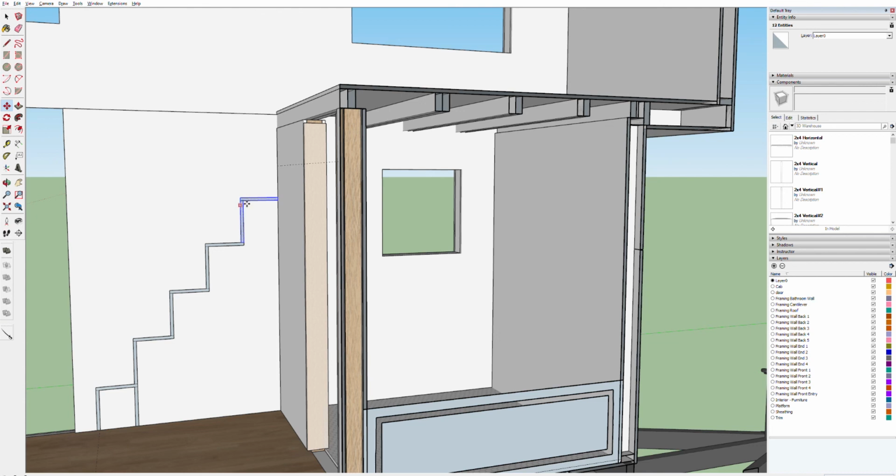Ooh, this is not right. Okay, so look, I did something wrong here. I miscalculated this. Ultimately, I wanted my last tread to stop up here. So what I actually need to do, it's funny, for those calculations in that calculator, I need to treat this with these 6 risers with the flush option, because I want this last tread to end at my total rise. Yeah, I kind of messed that up. Usually I'm used to going all the way up to the top, where this is fine because the last step goes to the top, but I'm not trying to do that here. I'm trying to terminate my last step at this point, which is not at the top of the rise. So I'm going to go back, change that option, and redraw this. Let me undo this stuff.